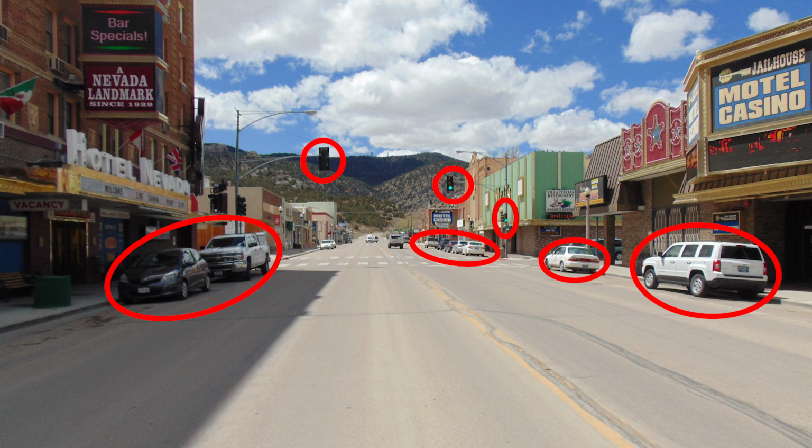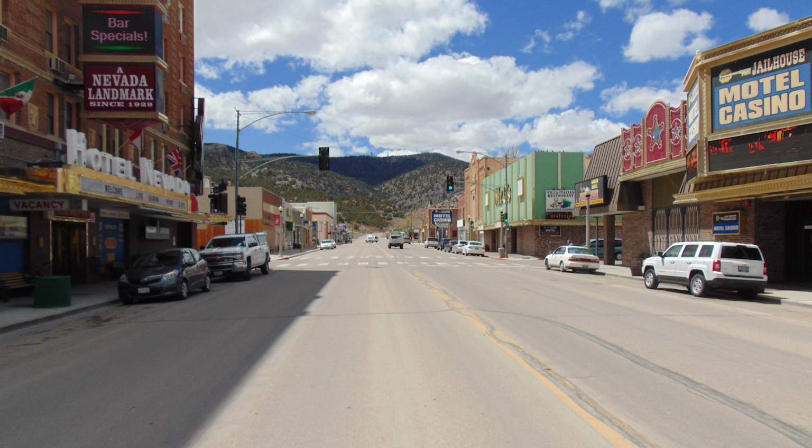First, you want to make sure the picture is suitable for using as a background of a roadway rendering. This means you probably want to get one with high resolution and good lighting, and preferably one without a lot of obstructions or undesirable vertical elements that you wouldn't want in the background of a finished rendering. Some examples of these undesirable elements are parked cars, pedestrians, light poles, or trees that ultimately might be out of place in a proposed condition.